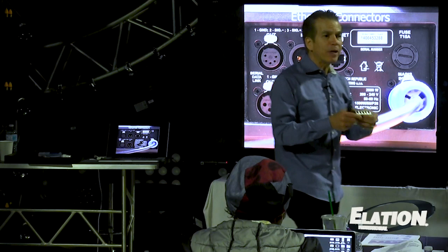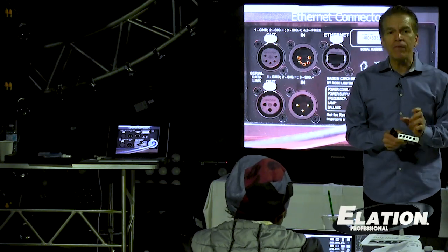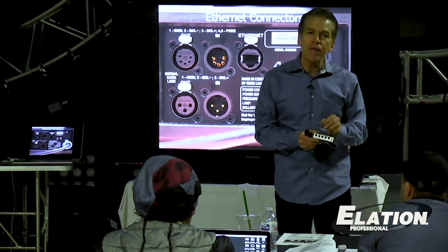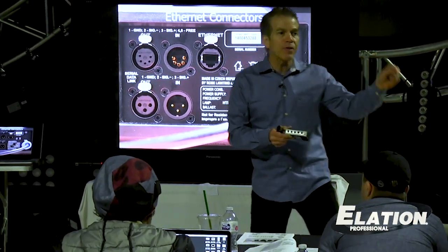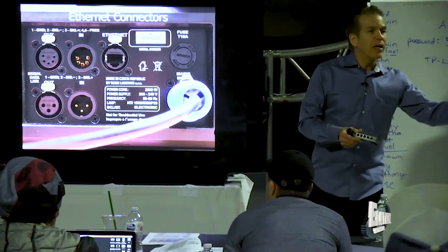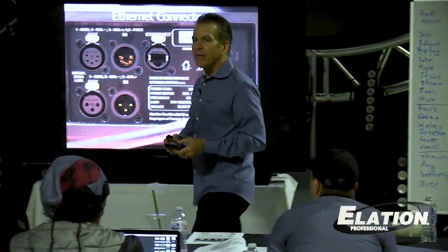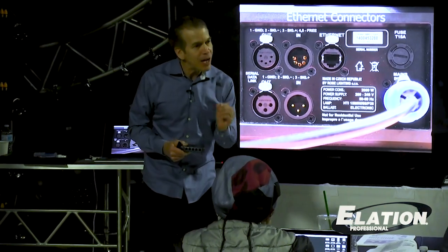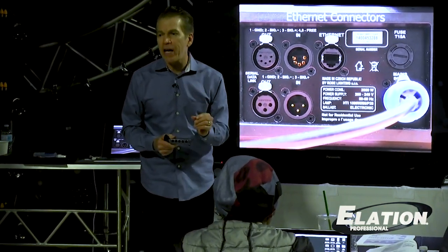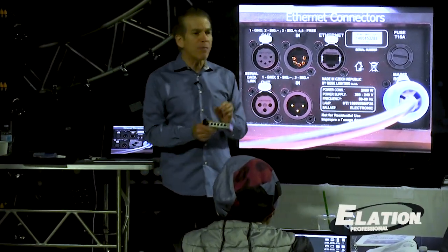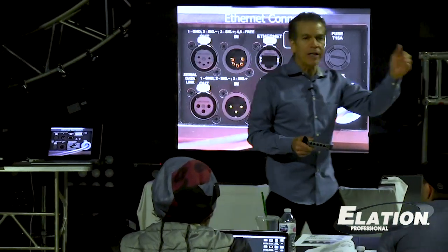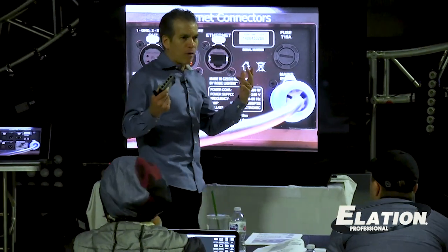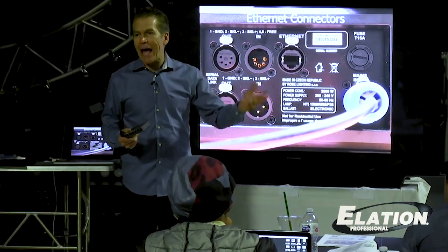The next fixture will get it, open the packet, read it, figure out what kind of data it is, where it's supposed to go, and if it's intended for another fixture, then it'll output it to the next one, and the next one, and the next one. The problem is that every time a switch has to read a packet, it takes time. It's latency. It's delay. And so by the time this fixture reads it, and then that one, and that one, and that one, a relatively high amount of time has lapsed.